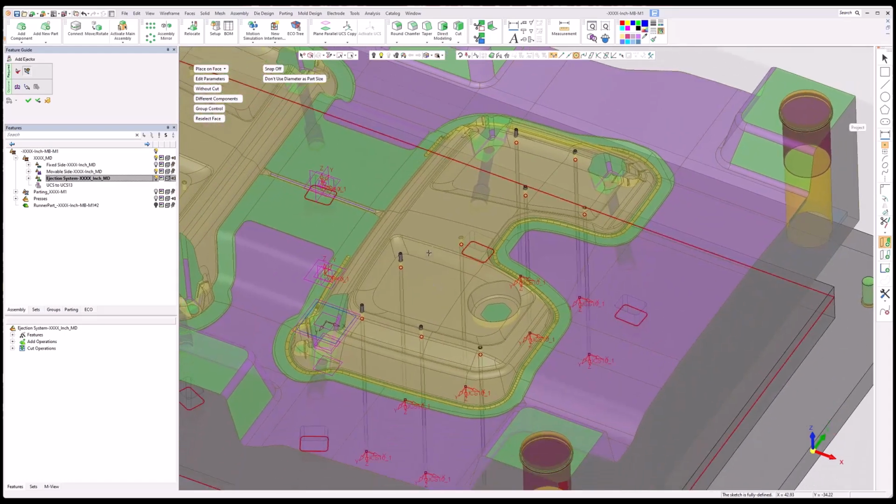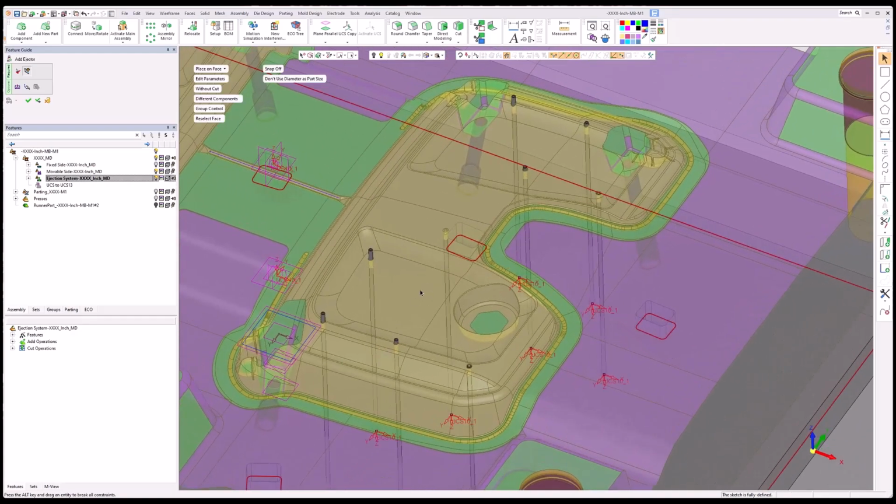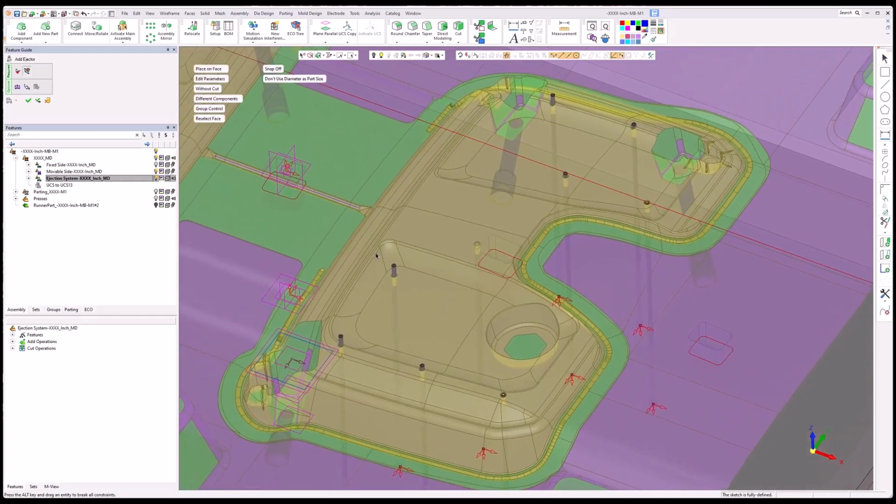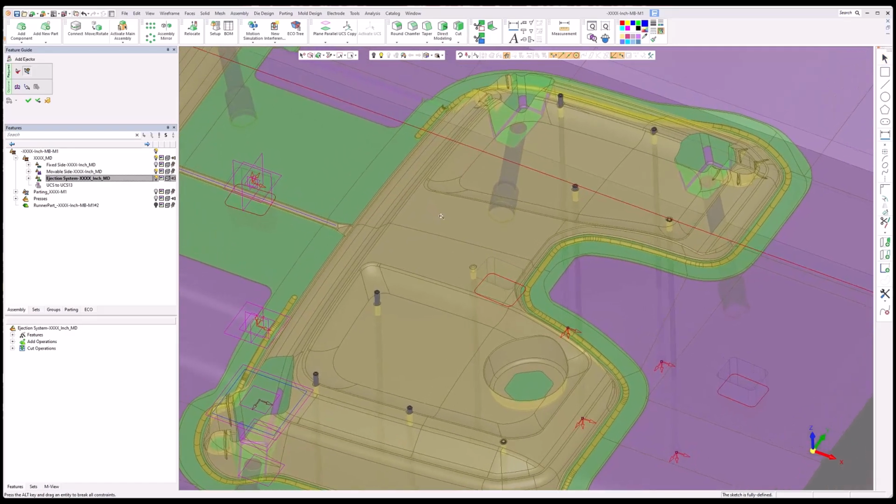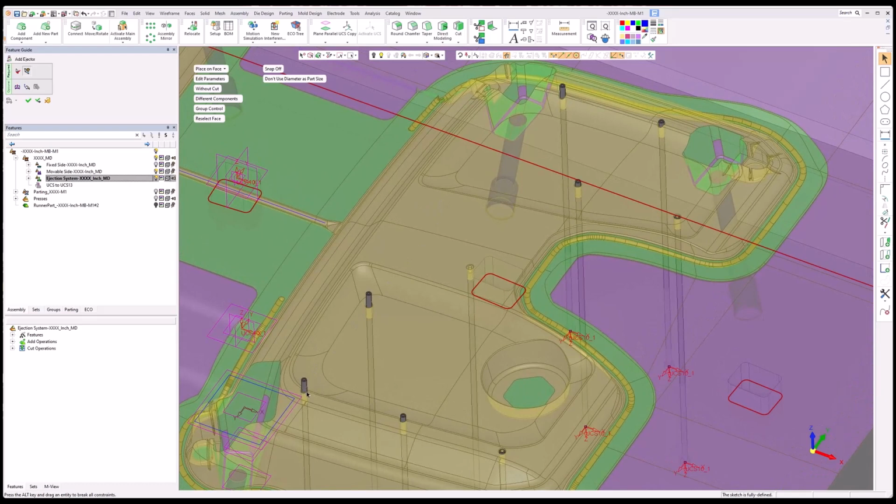The add rules for the length is normally very good, very accurate. One thing in this case: this geometry, I've had around for 10 years using this part, so it's a little old. I'm looking at these 3 pins here. They look to be a little long, and with ejector sleeves you have to be wary because there's only so much fit length or ream length at the top of them. I want to update these and see if I can go with a shorter one in these 3 areas.